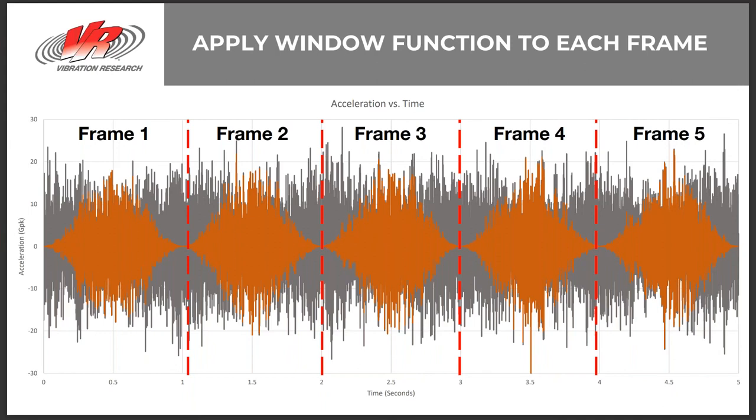So think of a terminal peak shock pulse. The sharp transition from the peak amplitude to 0 acceleration generates a much larger amount of high frequency energy than a smooth pulse like the half sine. For the FFT, that sharp transition between the beginning and end point is a discontinuity. That high frequency event affects the calculation, called spectral leakage. The windowing removes emphasis on the discontinuities and reduces the leakage effects.